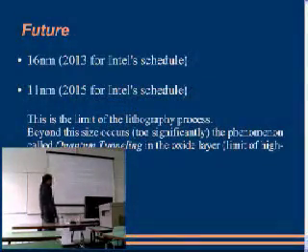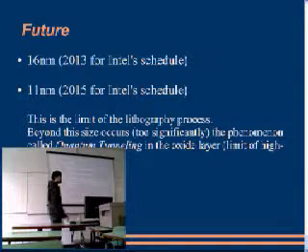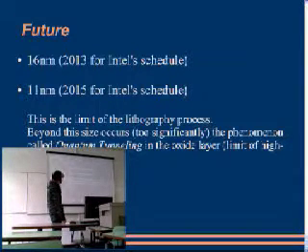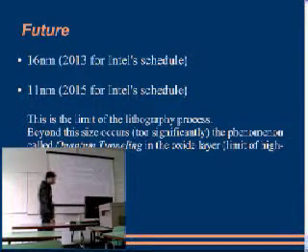What's the future of the technology of the FET transistors? In the Intel schedule, we have the 16 nanometer transistors, and in 2015, the 11 nanometer transistor. When we get to the 11 nanometer, we have a big problem, because the lithography process will not work anymore.